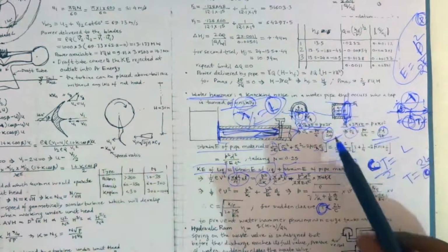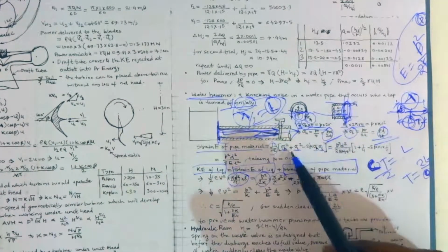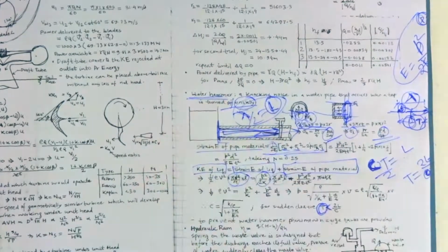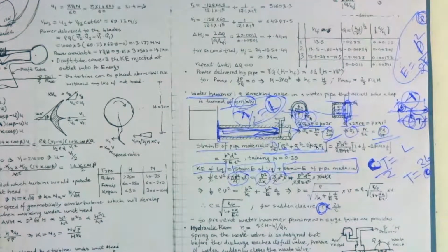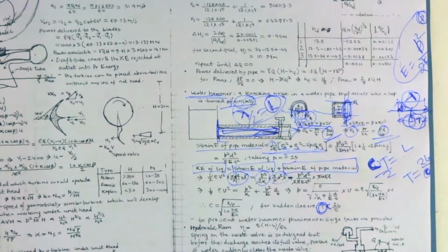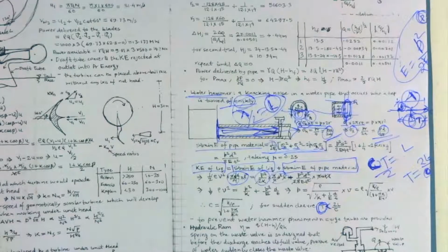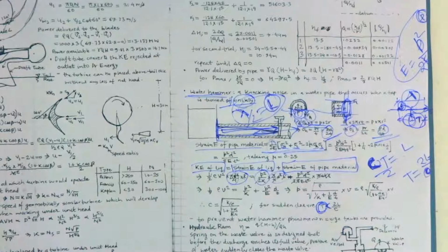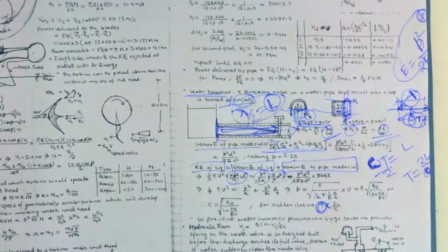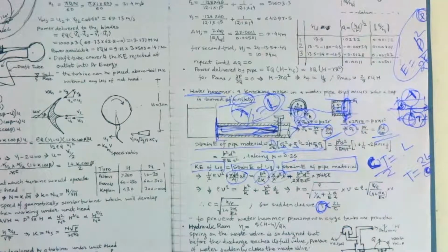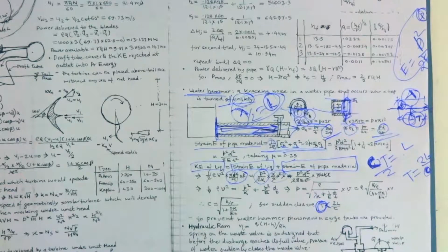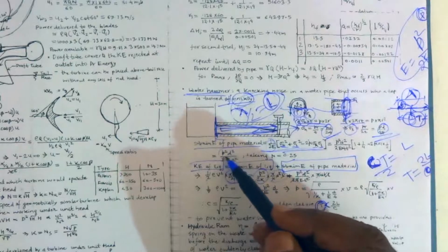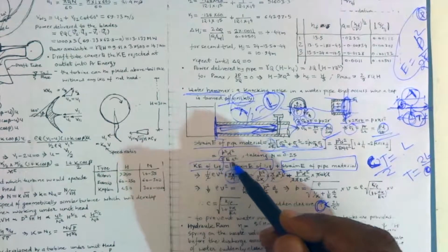We substitute these values in this energy formula: sigma 1 square plus sigma 2 square minus 2 mu sigma 1 sigma 2, over 2E. We get this very simple result: p square d square over 8 E t square.